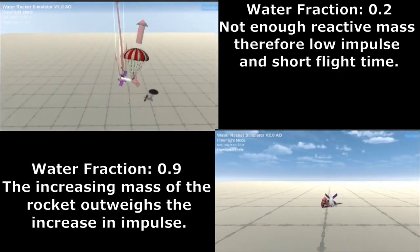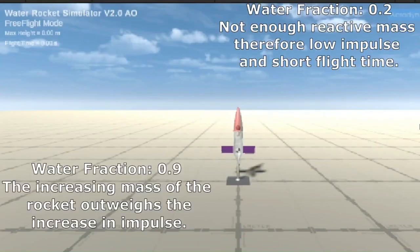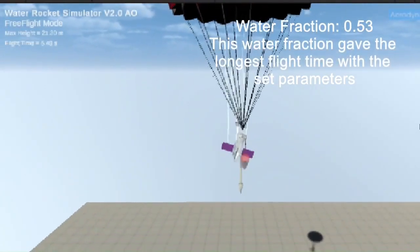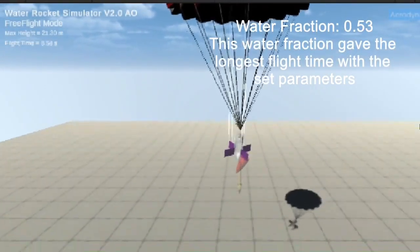The simulation in the bottom right has a high water fraction. In this case, the increasing mass of the rocket outweighs the increase in impulse, resulting in a short flight time. A water fraction of 0.53 projected the longest flight time for our rocket.